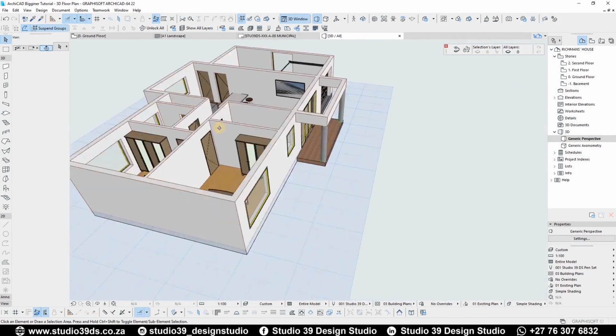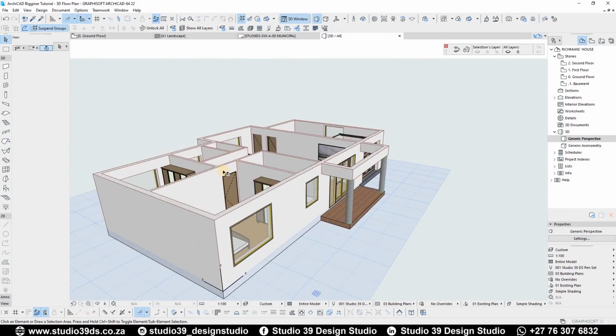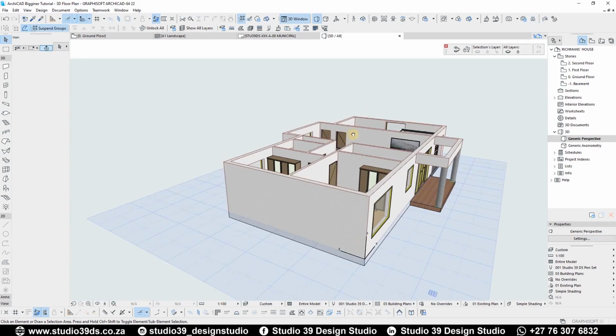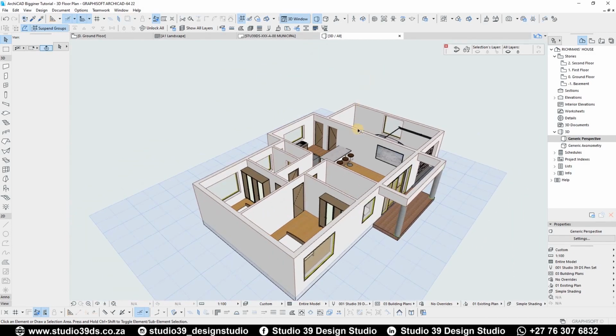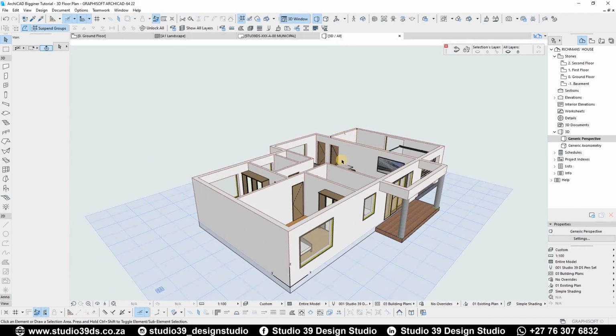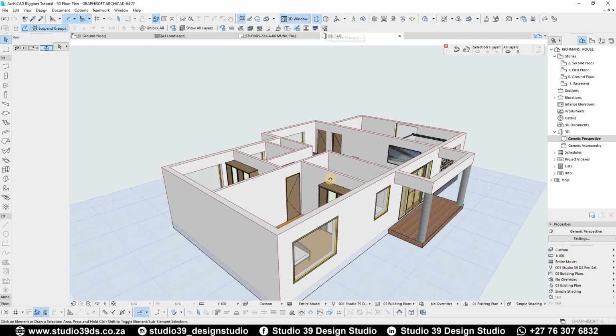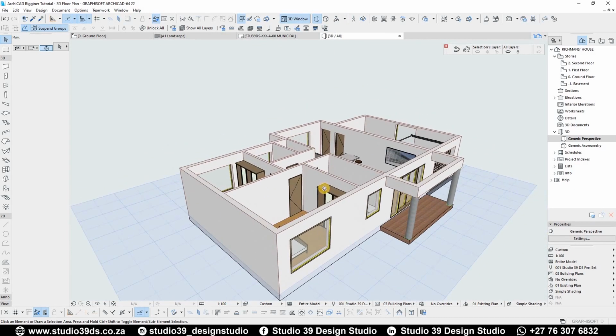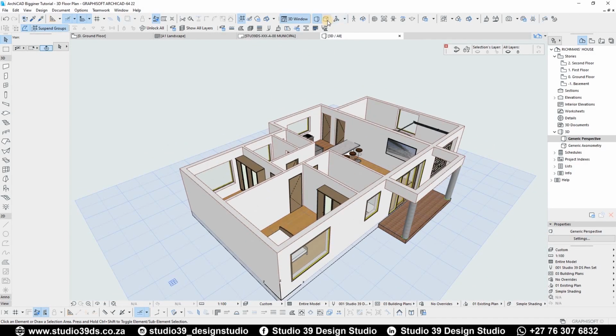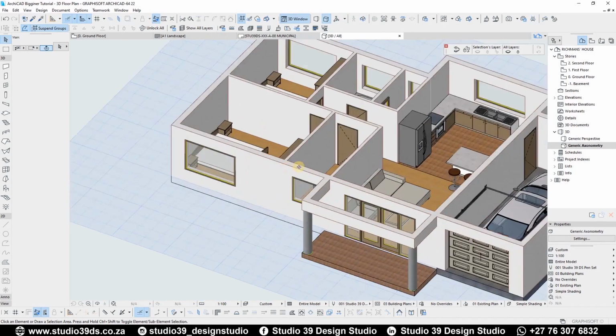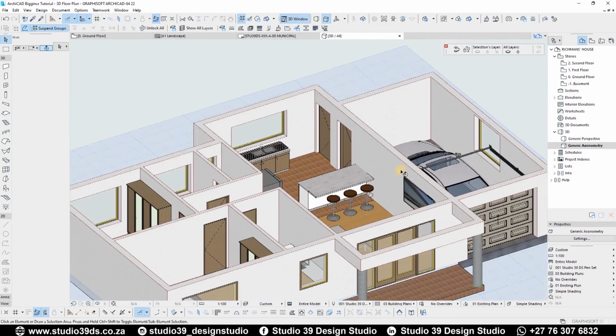We've gotten to this point, so now is to cut a plane vertically so that we can cut through the wall. There are many ways. I can manipulate the walls, but I don't think that's going to work out the way that I want. Another thing is I'm using a perspective, and 3D floor plans are better suited for an isometric, which is this one. That icon, you can press Control F3 if you want to go to that view right here.